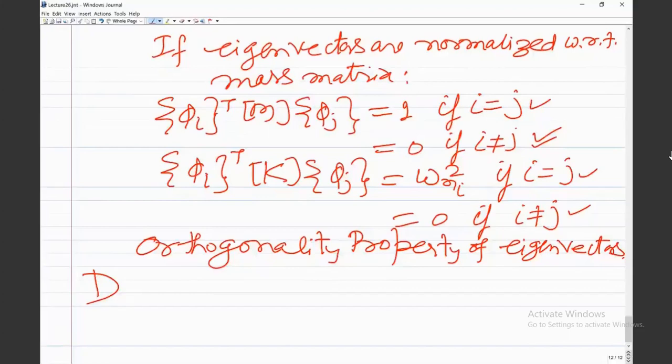If you are using an isoparametric element, you have to use the zeta eta coordinates. The interpolation I have already discussed is to satisfy the inter-element compatibility requirements. If you have an arbitrary quadrilateral in the physical coordinate space and formulate the element in that itself, it will not satisfy the inter-element compatibility requirements. That is why you go for the isoparametric element and assume the approximations for the displacement in the natural coordinates, so that it satisfies the inter-element compatibility requirement.